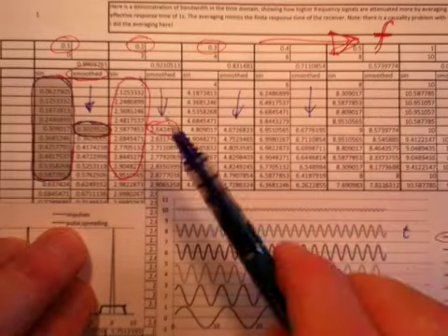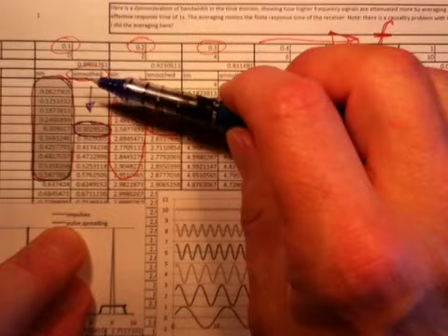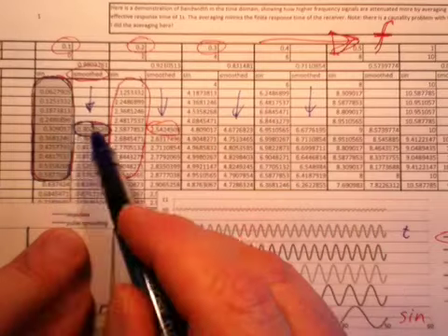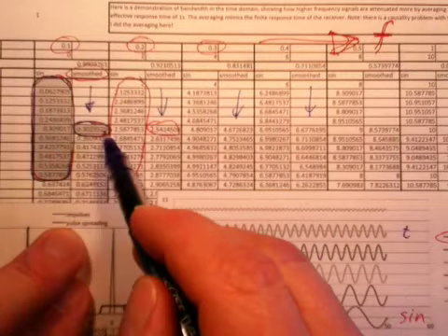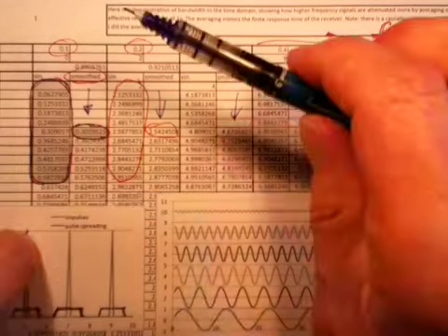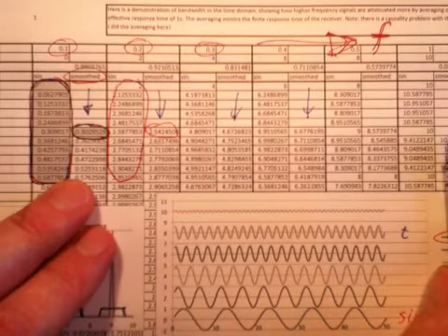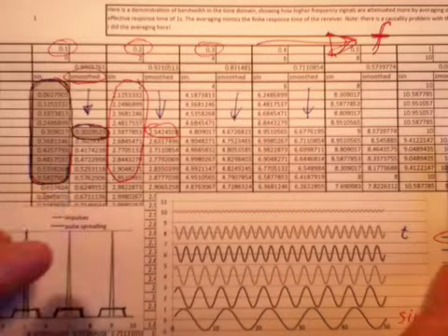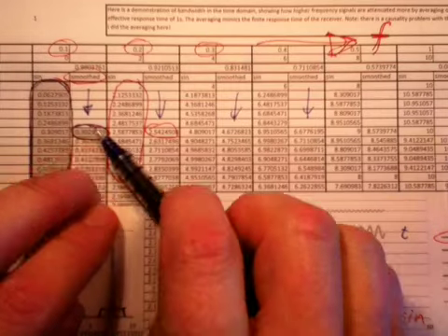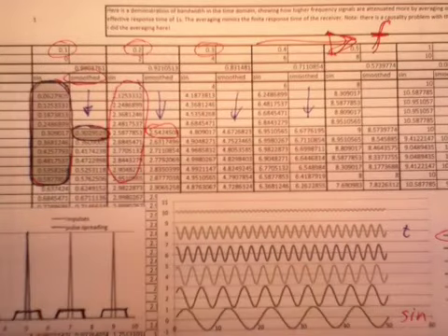And instead of plotting the sine waves themselves at these increasing frequencies, I'm plotting a smoothed version of them. Each point in the smoothed curve is the average of the values in its neighborhood time. So all these values that I circled are averaged to give this value. And then that running average is calculated throughout the whole curve. I do that smoothing for all of these sine waves, and that smoothing is effectively behaving like the pulse spreading. It causes each input piece to be spread out, so now this value comes from all of these values. This is characteristic of the pulse spreading, and it's also characteristic of the way real systems behave.